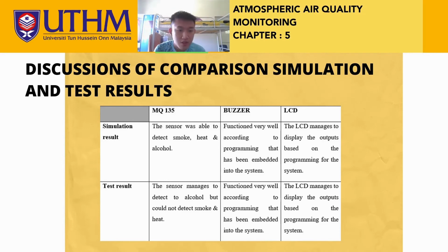So the simulation result for the MQ135 is able to detect smoke, heat and alcohol, but the actual test result only detects alcohol. But the buzzer and LCD function very well, which display the output and also alarm the user.